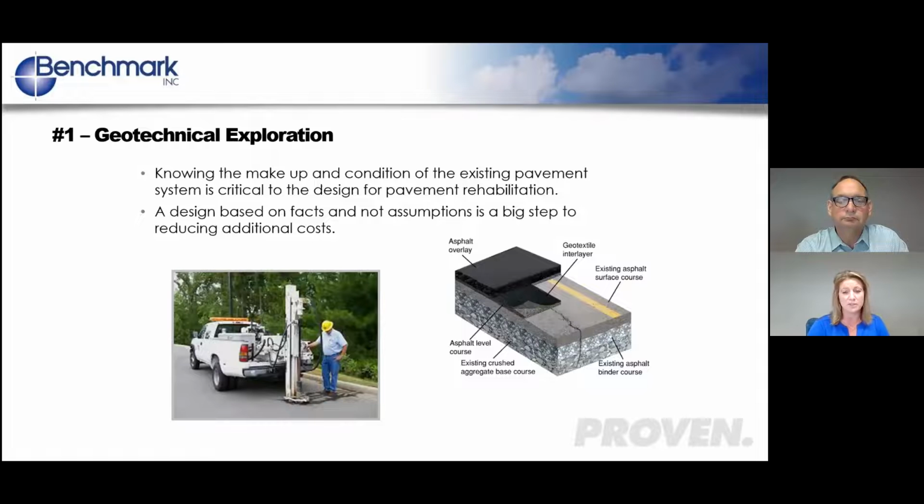So the first step is geotechnical exploration. Understanding the existing pavement system is key to a pavement project. It allows you to design the project based on facts and not assumptions, which allows you to have a more accurate design. A lot of times with geotechnical exploration, there's a cost to it. And most of the time it's happening while you're working through your design or project prep, and you might not even have the capital money yet to do the project. But it's definitely a good investment and something that will help you reduce the risk of change orders for your projects.